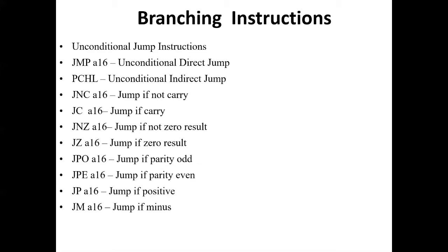PC means program counter. This instruction is used to jump to the address provided in HL register pair. Thus, it is an unconditional indirect jump instruction. Because of its indirect jump feature, it is not very commonly used. It is a 1-byte instruction compared with the direct jump instruction, which is 3 bytes long. Because of this size advantage, it can be useful for jumping to a frequently used portion of the program.